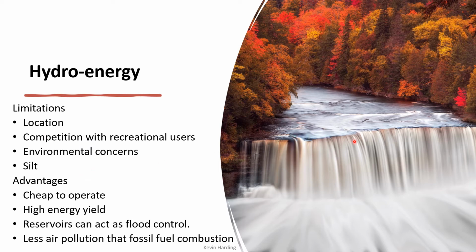Environmental concerns: the main concern is, if you've built a dam, how much water is going downstream now? Have you stopped the fish and the plants downstream from getting the water that they need? So that's why often you will always have one of the sluice gates open on these sorts of hydropower dams, to let some of the water down so that there isn't as much environmental concern.